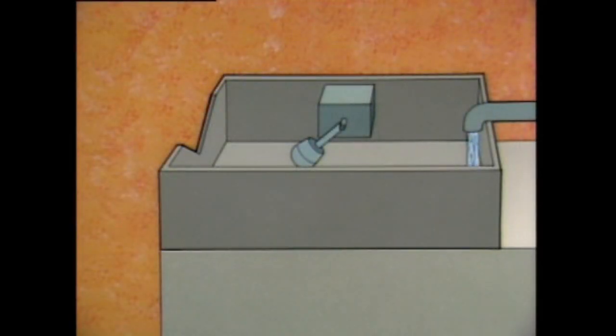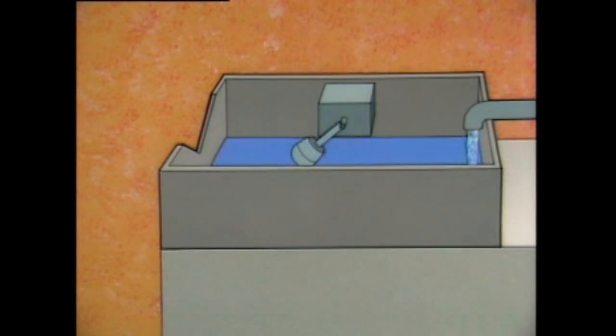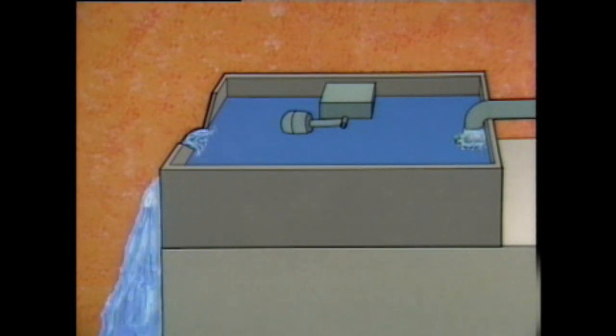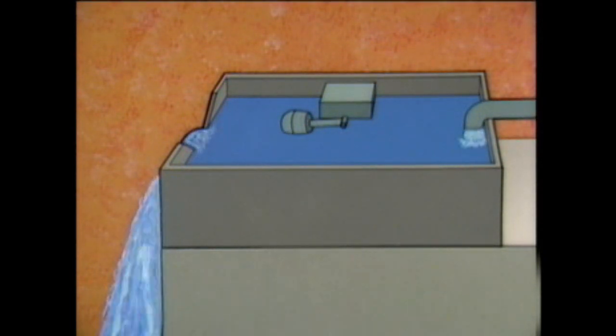In this arrangement, the level of the fluid behind the weir is used to determine flow rate indirectly. A weir works like this. When fluid enters the channel, it builds up behind the weir and overflows through the notch. The level in the channel stabilizes when the amount of fluid flowing through the notch equals the amount of fluid entering the channel. If the flow rate of the fluid entering the channel increases, the level behind the weir rises until an equal amount of fluid flows through the notch.